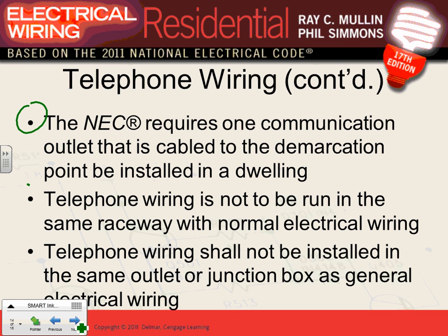Aaron, my friend, asks: can I put the phone line in the same conduit and box with power and light? No, just say no. Any low voltage system cannot be installed in a conduit, box, or cable with others, unless there's an exception, like going to the same machine. If I have a machine where power runs the machine and wires control the machine, I can put them in the same conduit or cable. Other than that, they have nothing to do with each other.